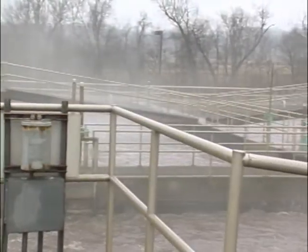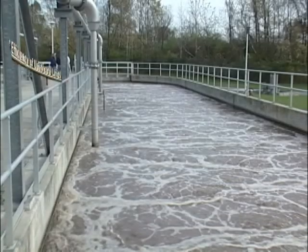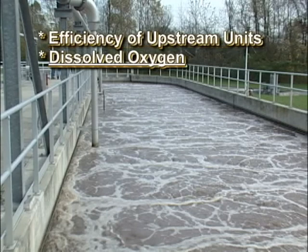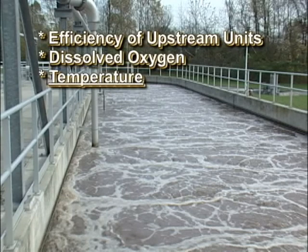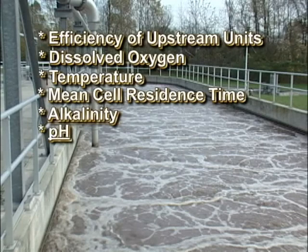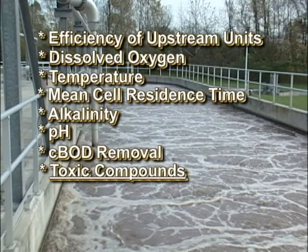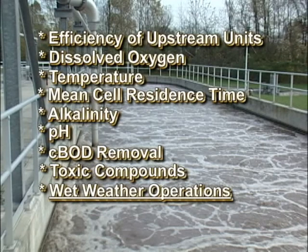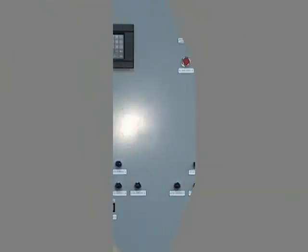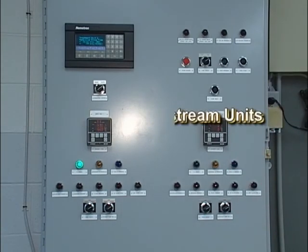Regardless of the process, there are a number of factors that impact nitrification. These factors include efficiency of upstream treatment units and processes, dissolved oxygen, temperature, mean cell residence time, alkalinity, pH, CBOD removal, toxic compounds, wet weather operations, and facility design. Let's take a closer look at each of these factors. Factor number 1, efficiency of upstream treatment units and processes.